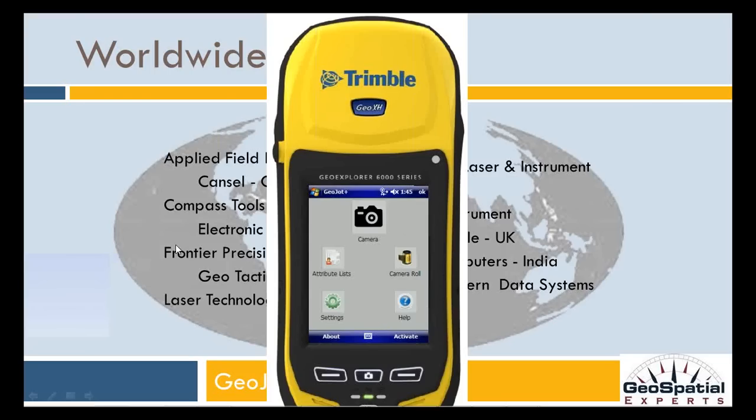Okay, and another question is about the laser rangefinder, asking if it can be used to offset the GPS coordinates, and the answer is yes. So with the GPS screen on, you can shoot a distance and bearing to an object, and that gets stored in the photo, and then GeoJot will calculate the offset location. So that's very useful if you can't get at the object you're trying to take a picture of to get its position. You can be across the street or across a field, and as long as you can shoot it with the laser rangefinder, then we will actually capture the offset location, not the location where you're standing when you took the photo.